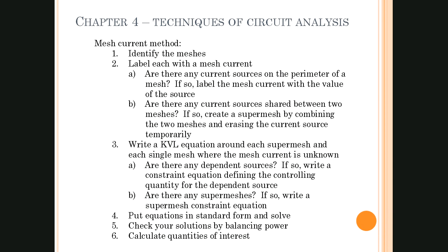Okay. And the techniques for mesh analysis. So step 1, identify the meshes. And I think we're all very good at that. Number 2, label each with a mesh current. And then ask yourself these questions to do the labeling.